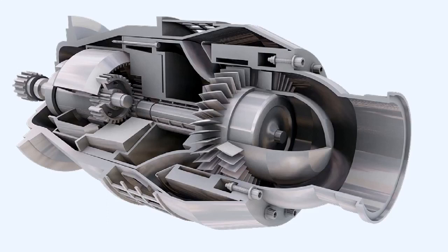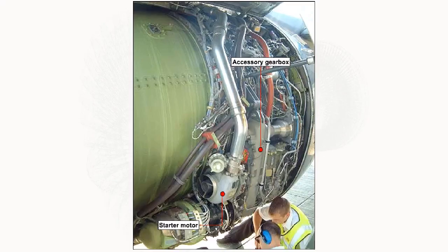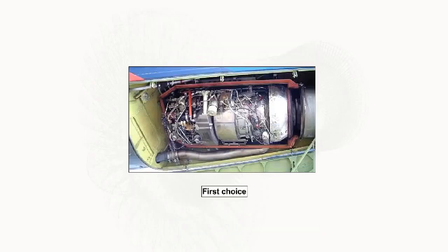The air starter motor is possibly the most popular starting system on large gas turbine engines. It's light, simple to use and very economical, insofar as it utilizes low-pressure air as its power source. The air starter motor is attached to the accessory gearbox of the engine. The sources of air available for engine start, in order of preference, are the Aircraft Auxiliary Power Unit, or APU. Use of an APU does not cost the airline anything, so it definitely will be the favourite method of supplying air for engine starting.